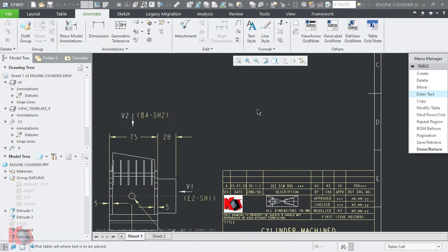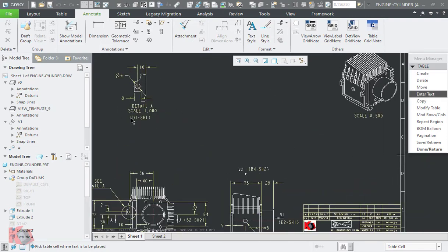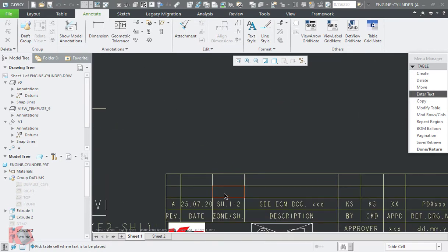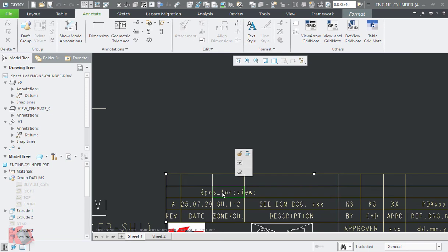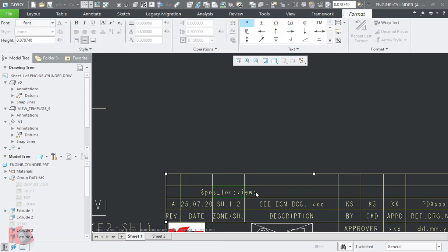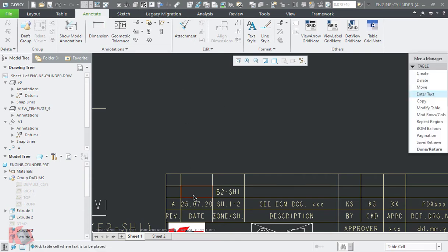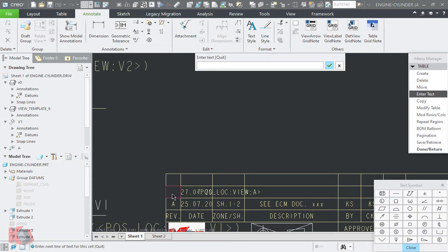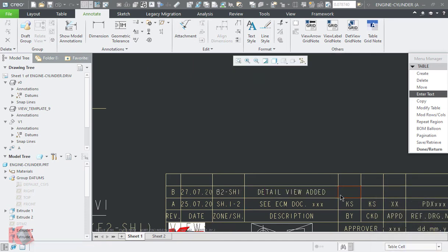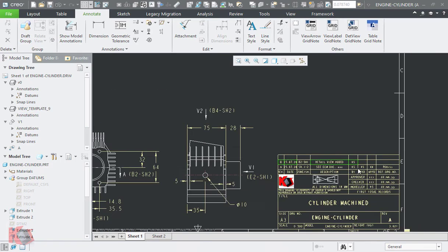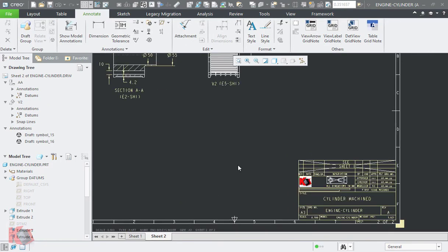And finally, when the document is revised for a particular view only, the view grid parameter can be utilized in the revision table also. I have automated this one too, as I did not want to worry about the parameter name, or typing it wrong in the first place. Like this example, I hope you would think of using mapkeys in your design process, and try to make them foolproof. This was the drawing part of using grid reference notes.